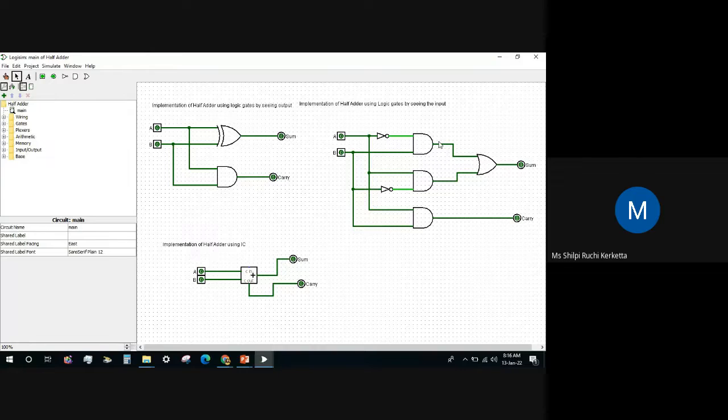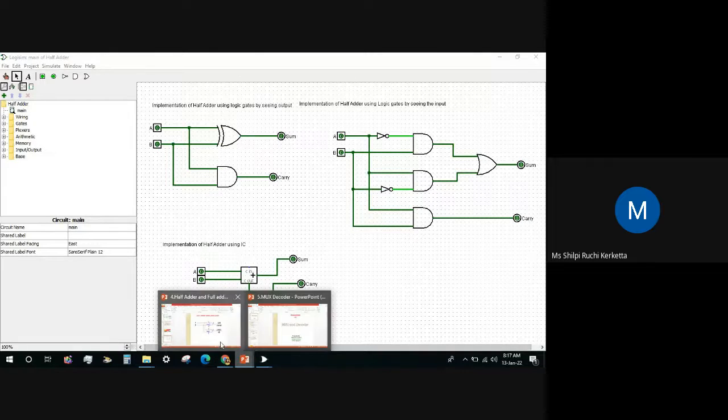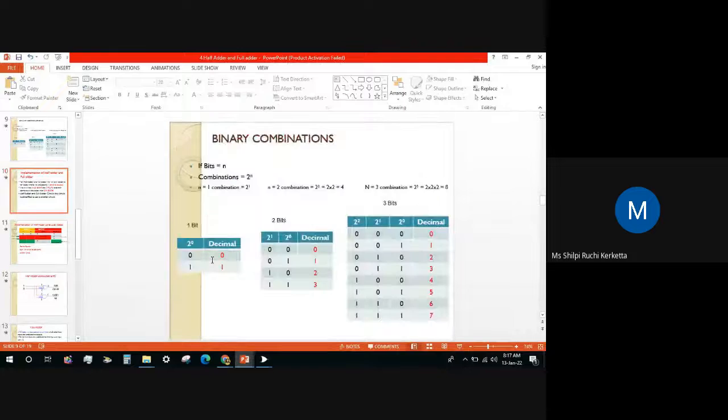We can even do this with the full circuit. Okay, so here we will need two AND gates and one OR gate and two NOT gates for making A dash into B dash. So this circuit will become very big. That's why we want to make a smaller circuit. So we only use this part. Okay. So we will go through the truth table.